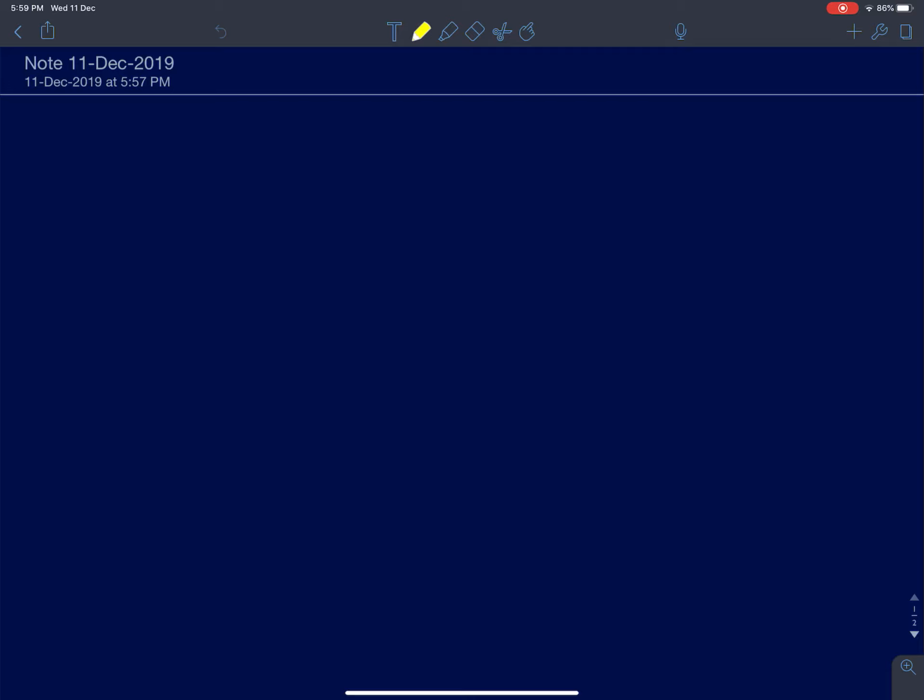For example, in receivers mainly we discussed noise figure, how to find noise figure given a circuit. I told you one of the easiest tricks, especially with circuits with very high input impedance, is to just find the input referred noise for the circuit and then divide it by 4kT RS. Here RS is the source resistance or the antenna's radiation resistance.